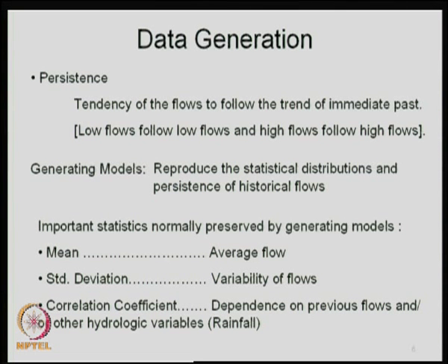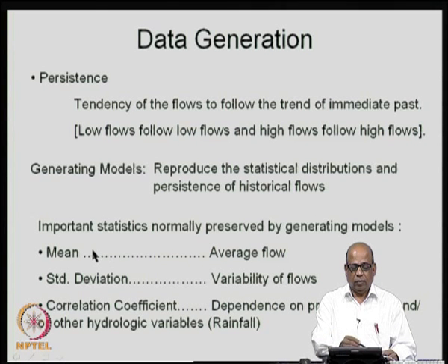So, we are capturing the dependence on previous flows or other hydrologic variables such as rainfall, soil moisture and so on, through the correlation coefficient. So, when we develop the generating models, we will develop them such that certain parameters or certain moments of the historical data are preserved in the sequence that we generate.